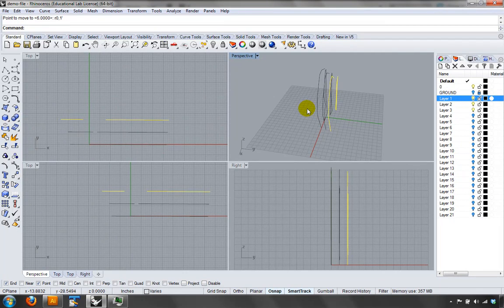The R stands for reference. If we just typed in a number, it would be an absolute coordinate, and we don't want that. We want a coordinate that is a reference to the original location, which is the 0 y. So R0 means don't move anything in the x, and comma 1 means move it 1 foot in reference to where you were in the y-axis, which just happens to be 0 in this case. So it makes it very easy for us. There's no reason why it has to be on the origin if you're using reference coordinates, but I think it just makes it clear.